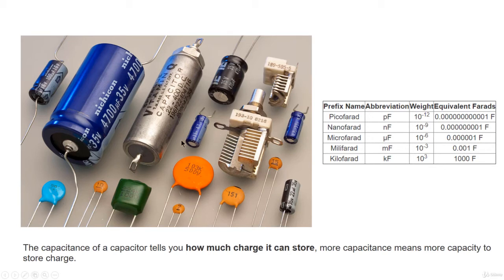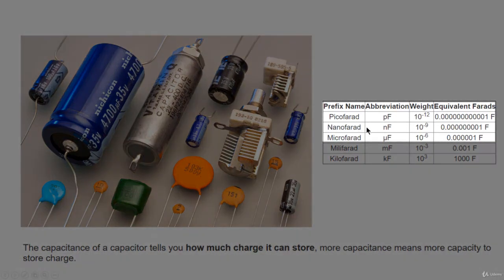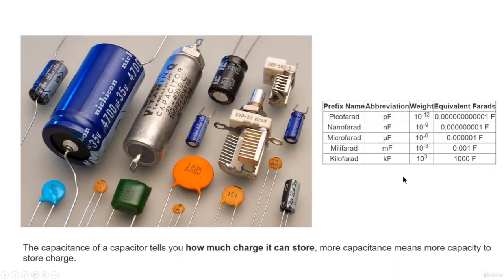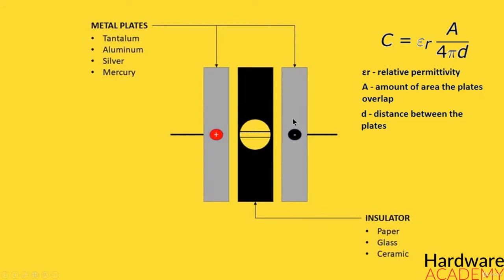So the standard unit of capacitance is called the farad, which is abbreviated as F. It turns out that a farad is a lot of capacitance. Even 0.001 farad is a big capacitor. Usually you will see capacitors rated in the pico, nano to microfarad range. When you get into the farad to kilofarad range of capacitance, you start talking about special capacitors called super or ultra capacitors.